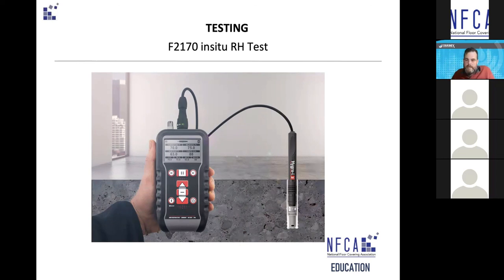think about it, concrete is always probably about 2 degrees cooler than the air. And the reason for that is evaporative cooling. So if anyone wants to know what evaporative cooling is, the way I look at it, because I have a simple mind, is the moisture needs energy to turn from a liquid to a vapor. And so whenever you have a surface where moisture is drying, it's using energy, in the form of heat, to evaporate. And it takes that heat out of the surface of something.